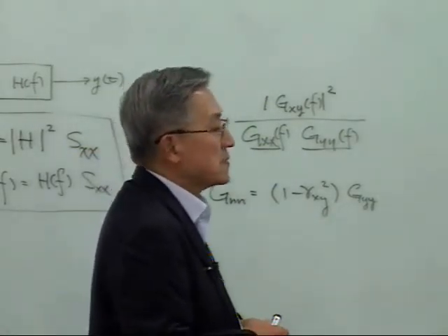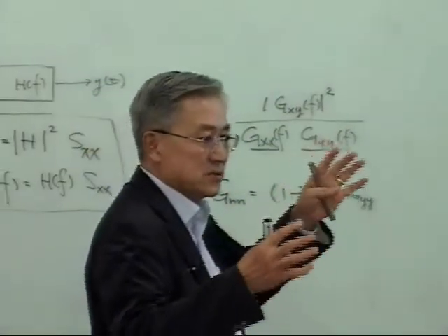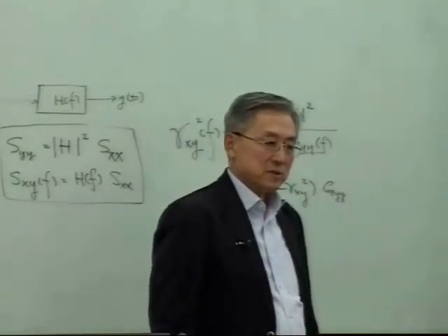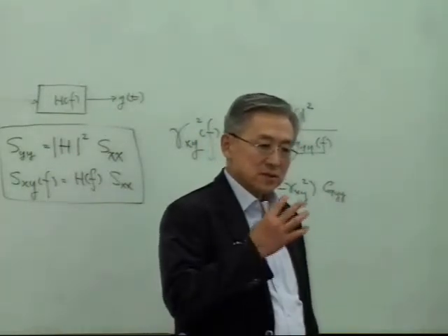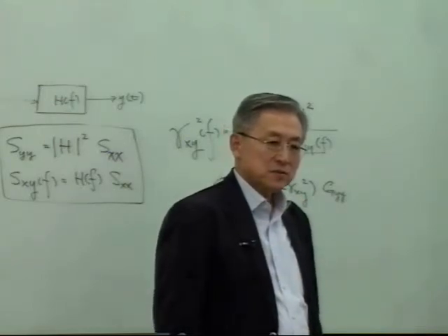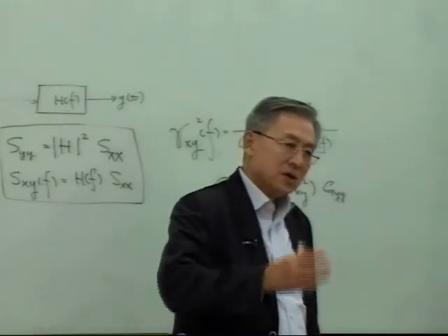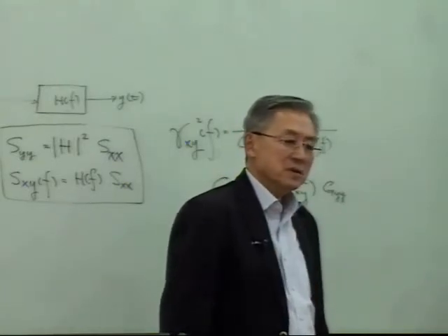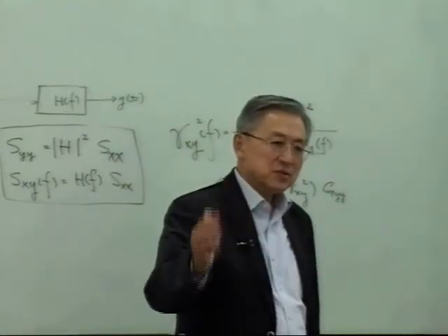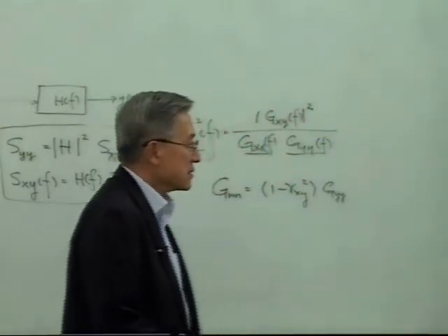So I usually ask about the situation in the system, then compute the noise spectrum, the power spectral density function for noise, and plot it. Then you can tell what the level of noise contamination would be. It's a frequency-dependent noise contamination.